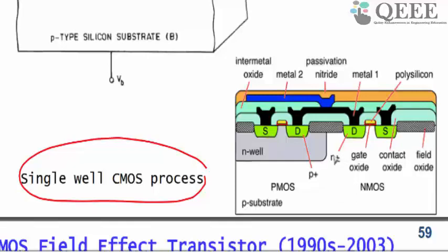Then you make the transistors, and later you interconnect them. Okay, so this is the top layer interconnect. For interconnecting they may use polysilicon, doped polysilicon, or maybe one or two metal lines. Okay, that was all there in the very early days.